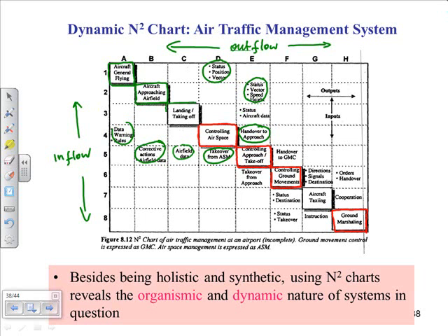This is now landing. The aircraft is about to land. Then it still has to provide the status, the aircraft position to this controlling approach. Also, taking off aircraft has to do the same thing, provide this information. Okay. Then let's move on to this one, controlling ground movements. Once the aircraft lands, then this system hands over control. So it hands over control to the ground movement control system. And this one gives feedback that it's taking over.